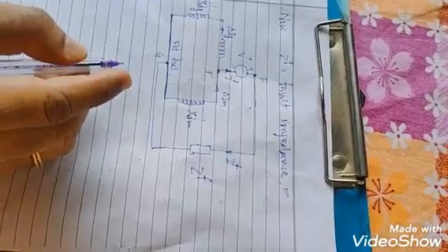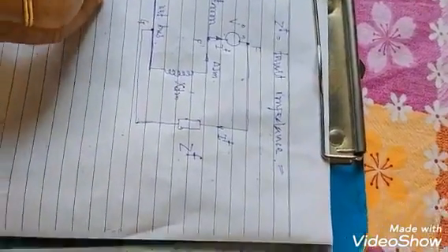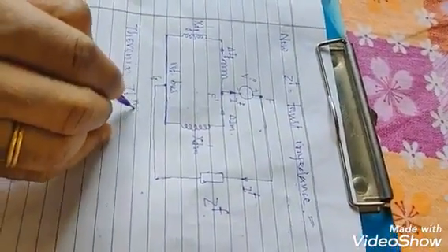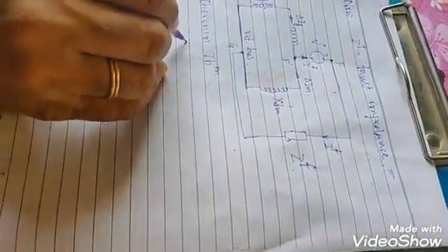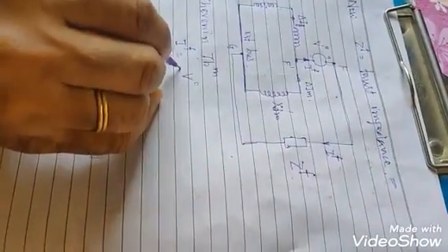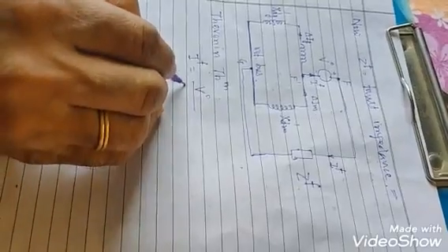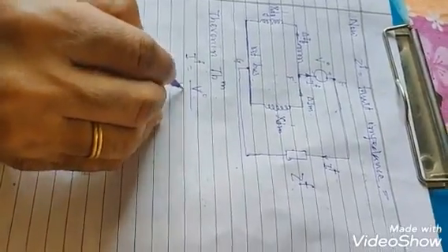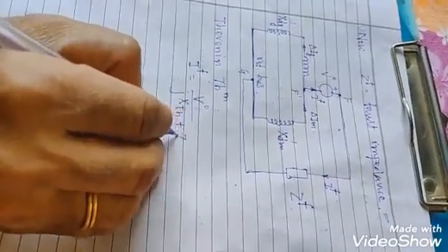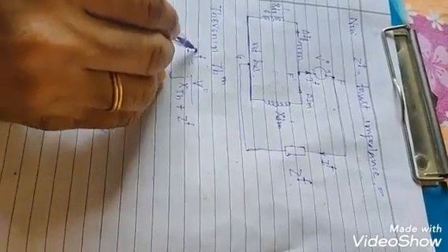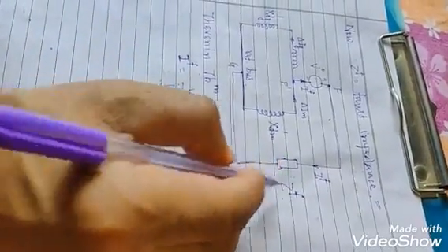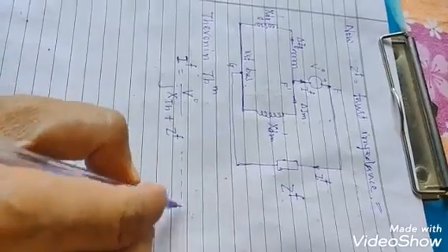Now from Thevenin theorem, we can write the fault current IF. This is equal to Thevenin voltage V0, the pre-fault voltage, upon Thevenin impedance jXTH plus fault impedance ZF. This is the current through fault impedance ZF. Suppose this is equation 1.